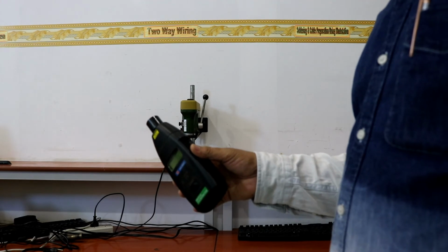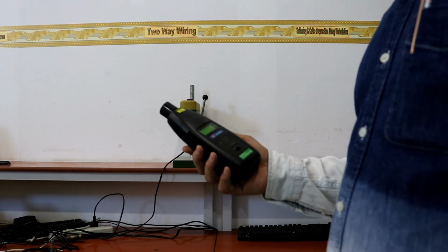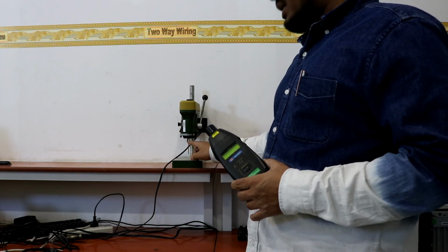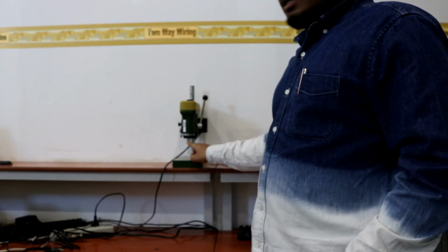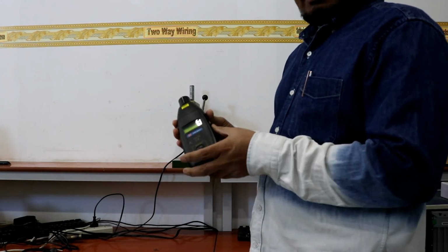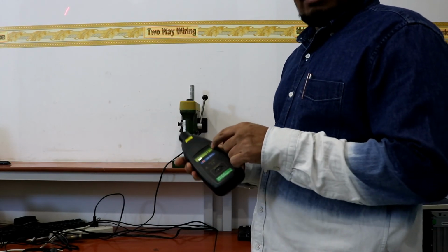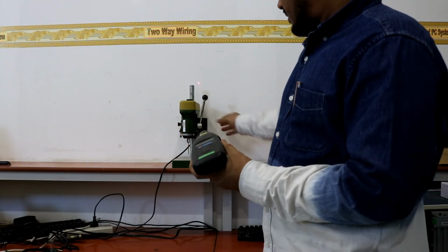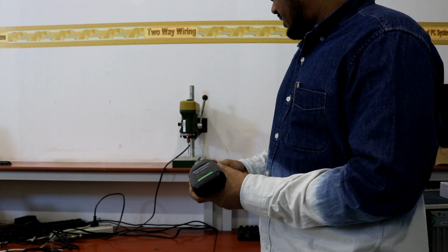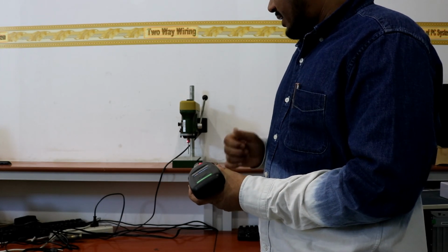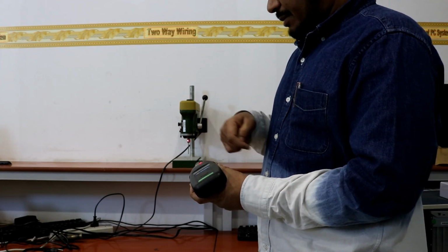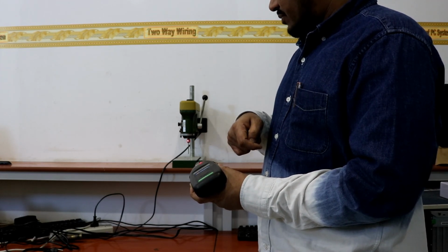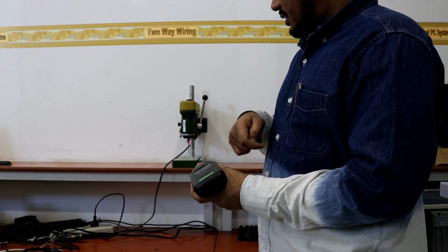I hope you understand well. I will once again repeat that we need a reflecting mark on the rotating object here, and we have to continuously press this button so that a zero reading will come and a laser light will come out. Now when you are pressing, I am keeping this here and the reading is coming out 4500, 4800, because it's fluctuating based on the voltage and motor condition.